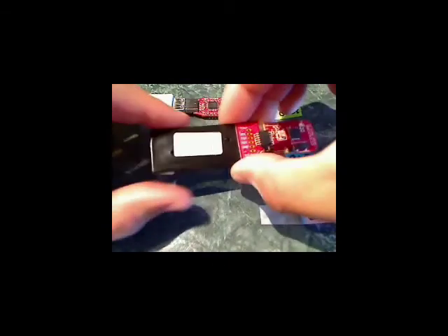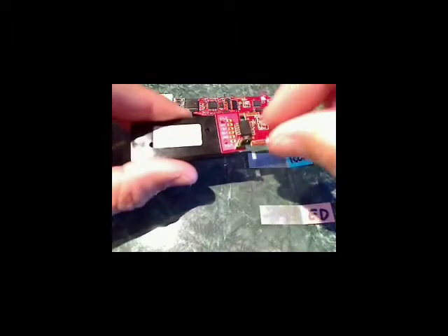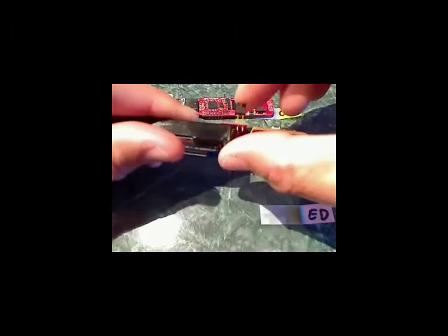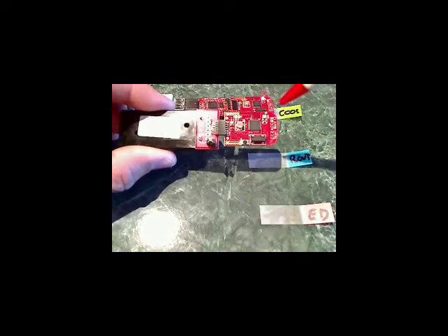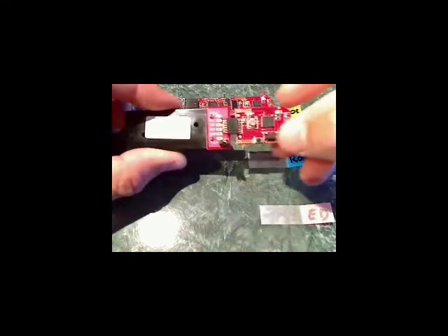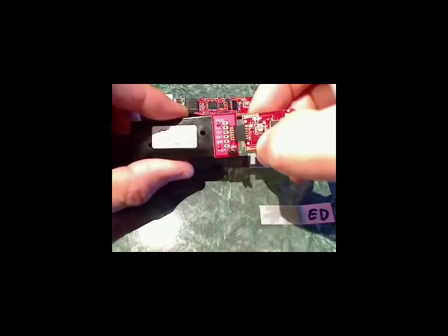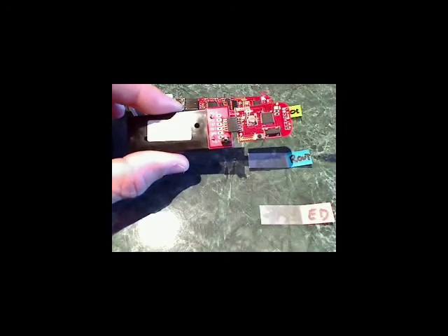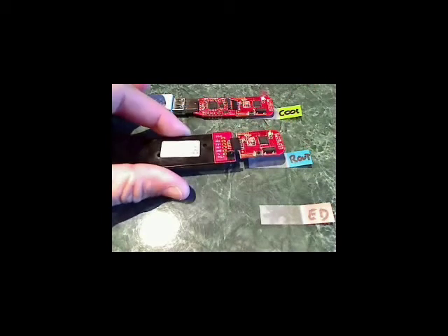So I'm going to take one of the other boards right now. I'm going to power it by connecting the jumper. Board is in the exact same place. Both LEDs are blinking. And now I'm going to press the button on the board again once. Now it will detect the coordinator, and it will set itself up as the router. And I don't know if you can see, but the green LED is lit right here, indicating that it's the router.